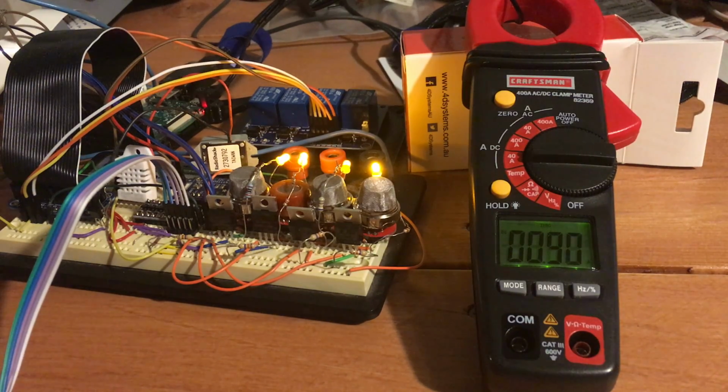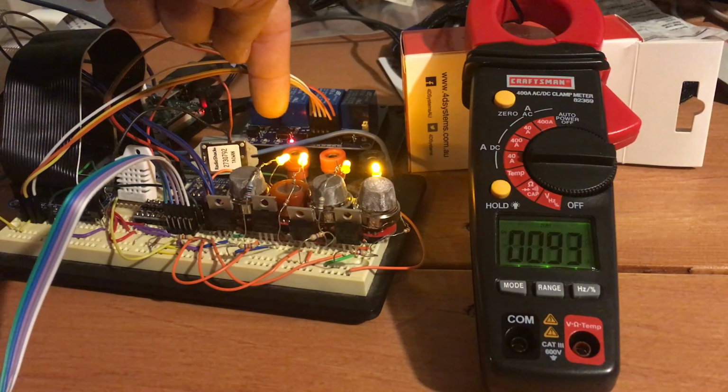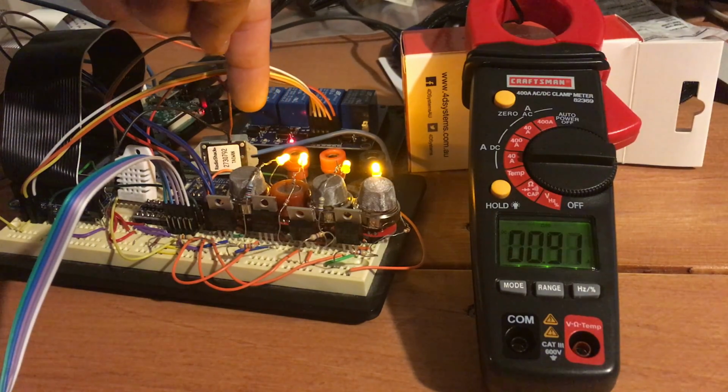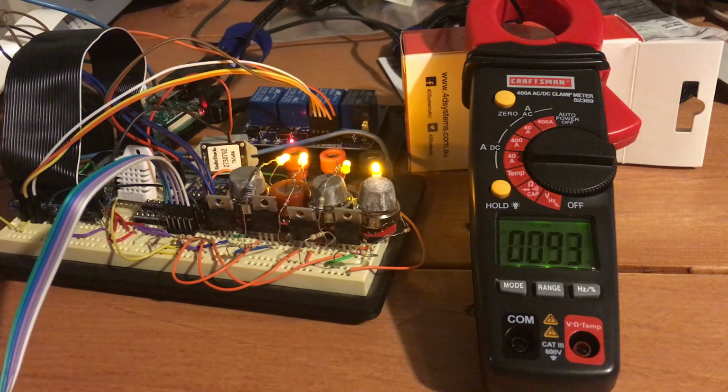Just with the 4 heaters, and I can turn on a light relay, so you can see that red light in the background come on right here. And if I turn on another one, and these will try to keep turning off because automatic will take over, but we're at about an amp for the total draw so far, and that's on a 2.5 amp power supply, so we're doing good.